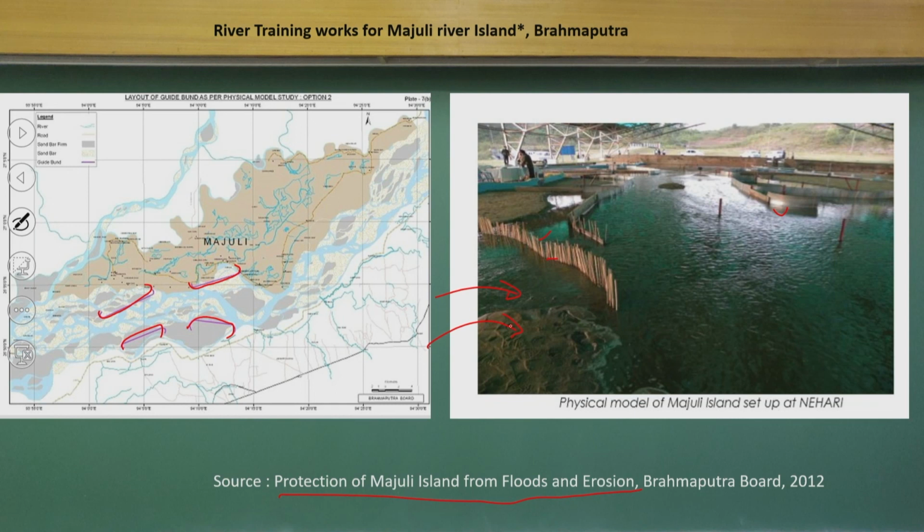So, first a series of physical experiments is done to know how the flow happens, the scour hole formations, the channel deepening, and how effective impermeable or permeable spurs are, by measuring flow, velocity and streamlines under different flow conditions like the 5-year, 10-year or 50-year return period flood. Then we can implement the same on these rivers.